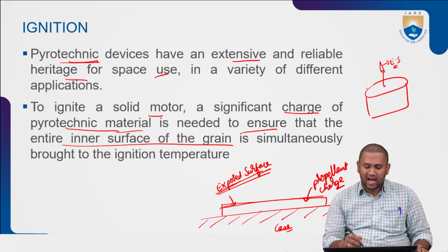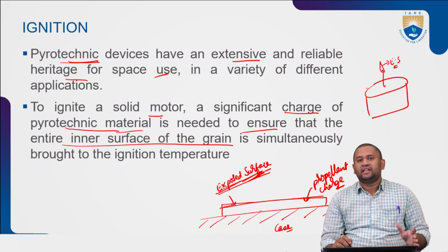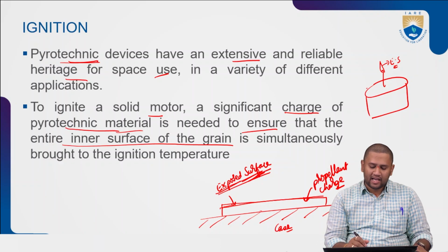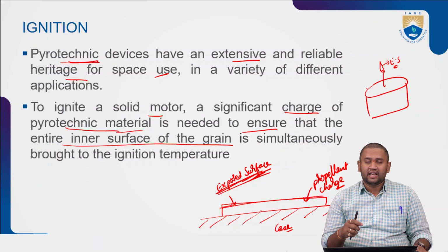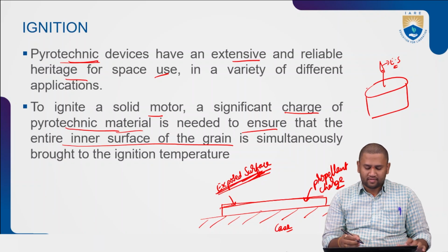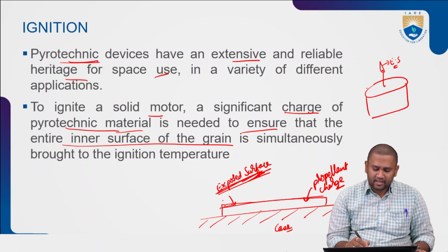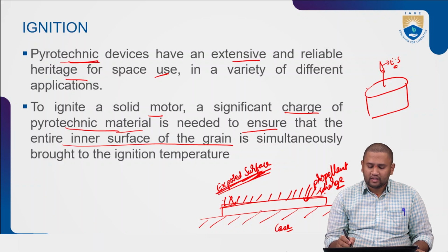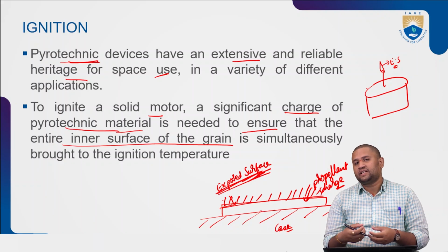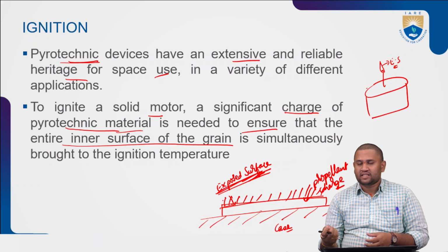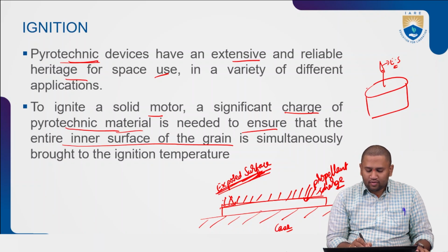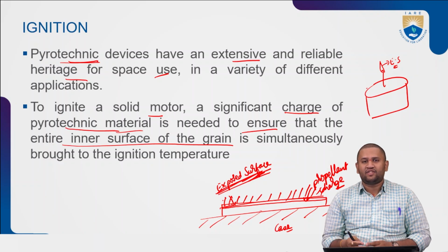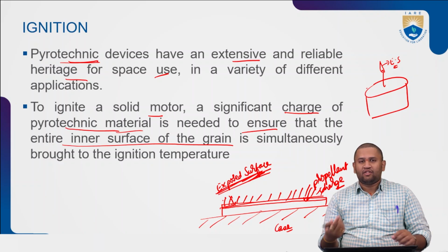To start burning. Now, as soon as it starts to burn, it tends to move further. As the upper layer gets converted and burned into combustible gases or exhaust gases, the lower layer tends to evaporate further and convert itself into gaseous form, then you burn again.